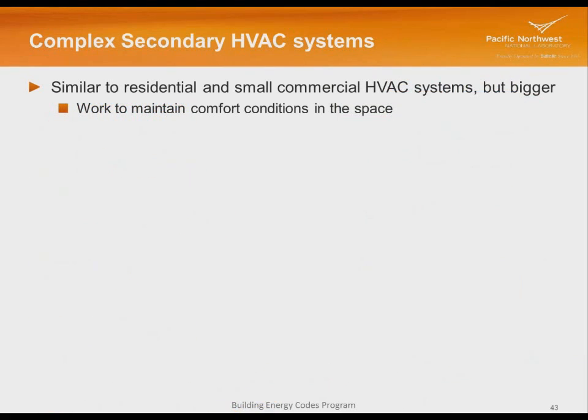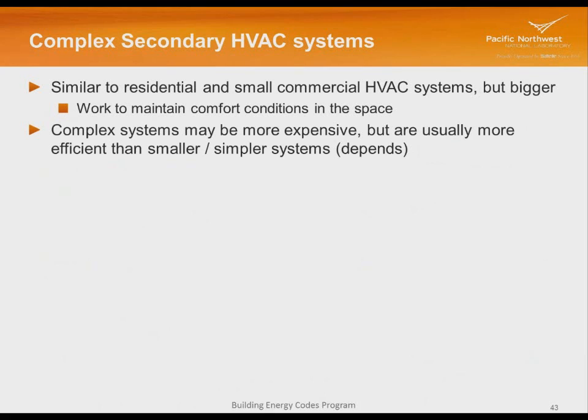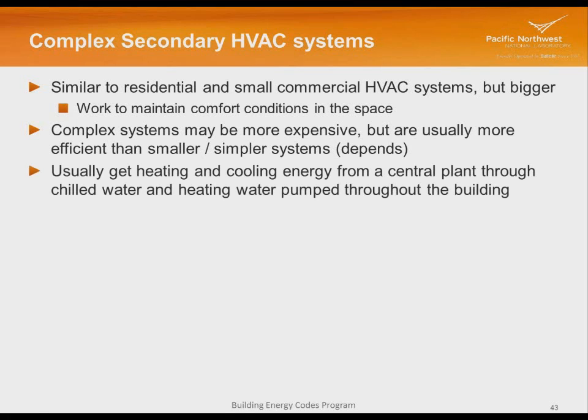In a larger, more complex building, these large systems are similar to residential and small commercial HVAC systems, but they're bigger, and there are more moving parts to them, if you will. They work to maintain the comfort in the space just as the small systems do. They may be more expensive, but they're usually more efficient than smaller, simpler systems. That depends. Sometimes all those extra pumps and different controls with reheat systems may not be as efficient as just having a bunch of individual single zone systems. It depends on how efficient a single zone system you get.